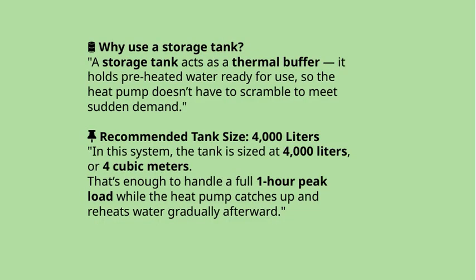So, why do we use a storage tank in this type of system? Well, think of it as a thermal buffer. It holds preheated water, making it readily available for use when needed. This way, the heat pump doesn't have to scramble to meet sudden demands. It's like having a reserve of hot water ready to go, ensuring smooth and efficient operation.